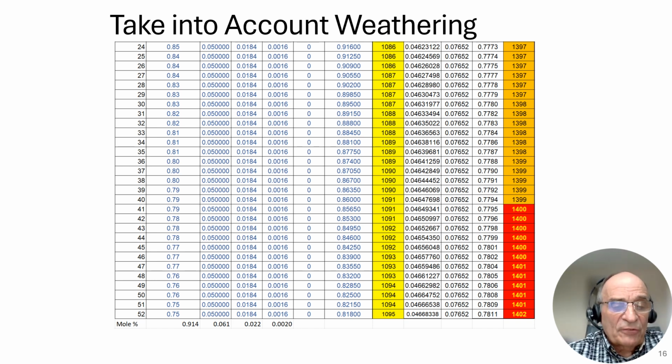What has happened is preferentially the methane has boiled off, the ethane has remained the same, and the propane has remained the same. Thus, if you look at the total mixture, you see that it is now a lesser percentage of methane and a higher percentage of the higher heating value components of ethane and propane. And that's why when you're selecting a site, you have to make sure that your feed gas is appropriate for the LNG that you want to make. And if it's not appropriate, you're going to have to do some more pretreatment. The more pretreatment you do, the more costly the plant will be.